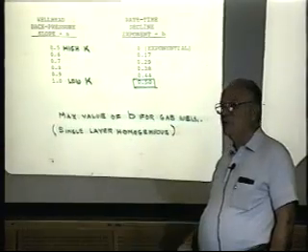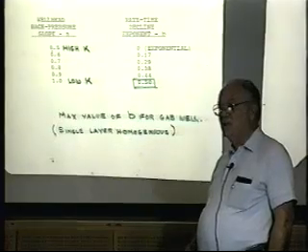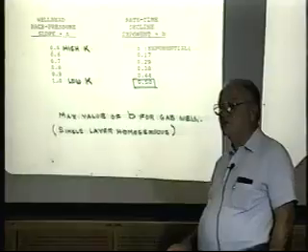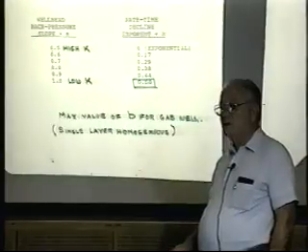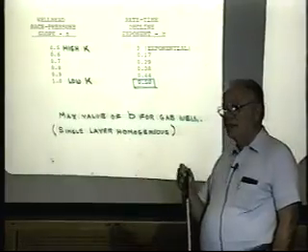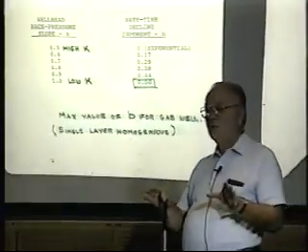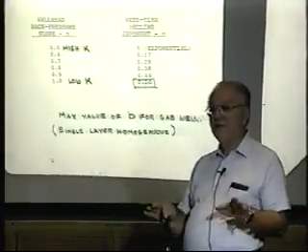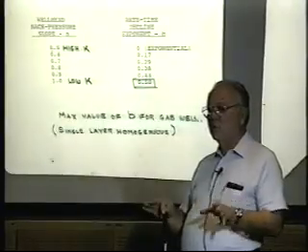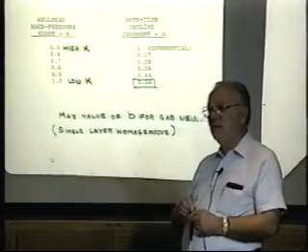It should have been cased and individually stimulated. In the early wells, we did do the individual stimulation with bridge plugs. And I'll show you some field examples, some old reports of how a lot of these reservoirs were originally completed in open hole with a commingled stimulation.